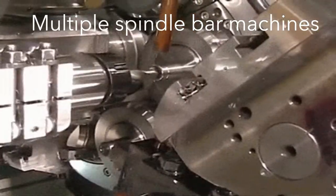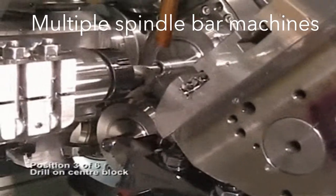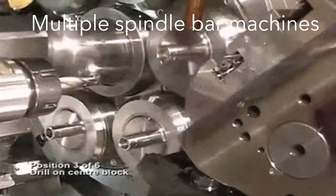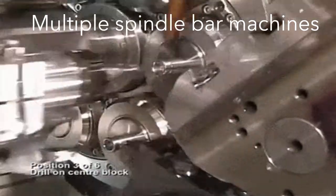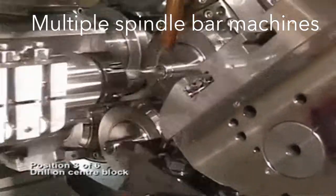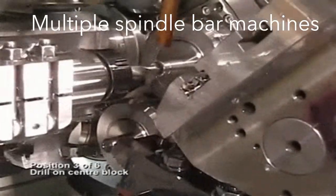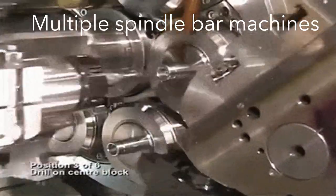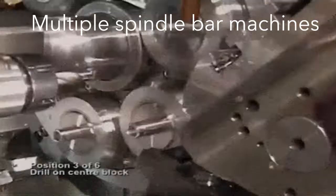Multiple spindle bar machines are also available. These machines have more than one spindle, so multiple parts are machined at the same time by multiple tools. For example, a six-spindle automatic bar machine works on six parts at the same time. At the end of each machining cycle, the spindles, including the collets and the work parts, are indexed to the next position.